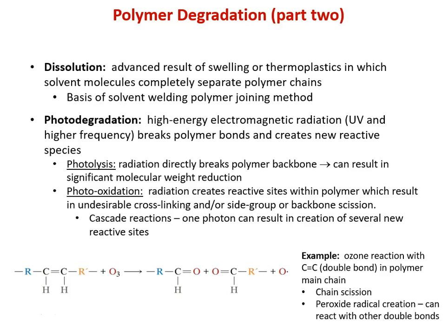And again, that dissolution is like swelling. It's relying on overcoming secondary bonds. But if we're looking back at disrupting our primary bonds, we had mentioned that up till now, from the last slide, it took a pretty powerful oxidizer to do that. We can also do it with light. Ultraviolet radiation has a high enough energy to break the main chain of a lot of different polymer species, especially aromatics, which unfortunately are some of our stronger polymers and are used for structural applications in things like Kevlar, some of our high-strength fiber polymers.